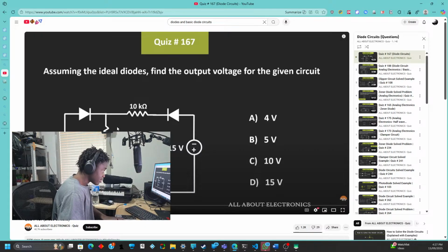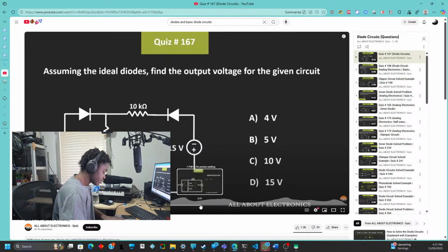This is connected to the source, and since this diode is here and it's negative, there's two sources. I'm just going to assume this is off for now and keep this off, and then use superposition to solve it later. So I'm doing just this one, and because we have a diode here, I'm assuming it's an open circuit here. So 10 volts.